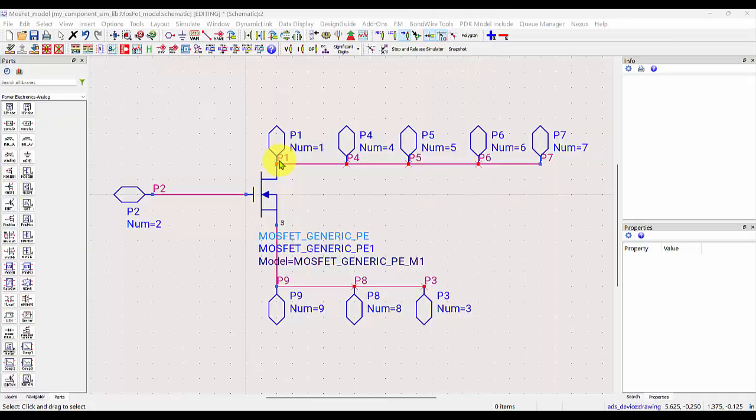I would also like to draw your attention to the fact that when synchronizing the pins from the layout to the schematic, a wire label is added to each pin, P4, P5, and so on. The problem here is when you have different wire labels at the same connection, the pins are disconnected from the transistor, and therefore you have to delete this wire label.